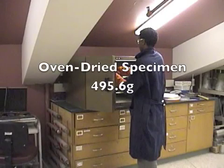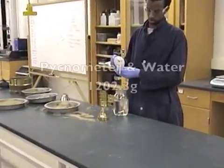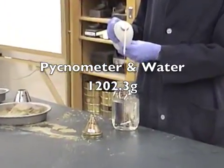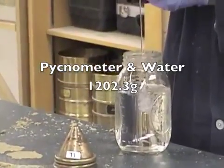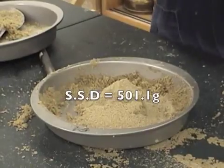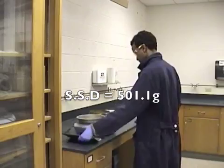For our example, let's assume that A, the weight of the oven dry specimen, is 495.6 grams. For B, the weight of the mason jar with just the water, let's assume our weight is 1,202.3 grams. Let's assume that S, the weight of the saturated surface dry specimen, is 501.1 grams.